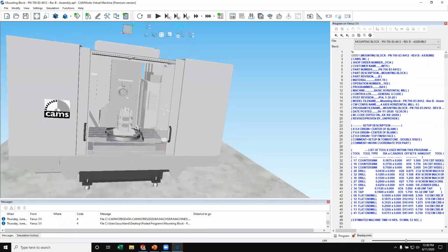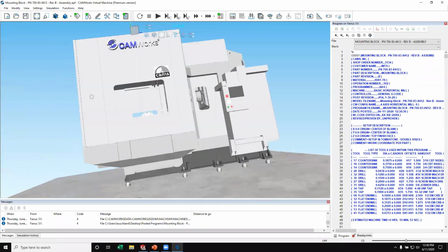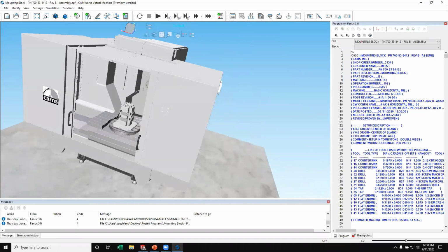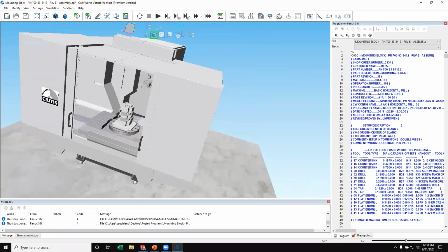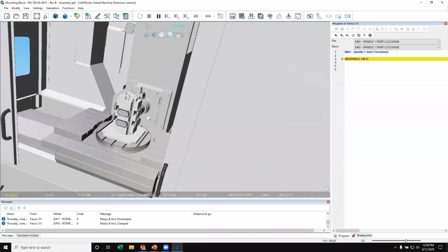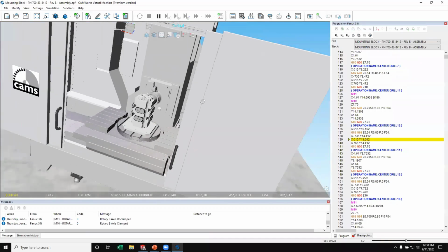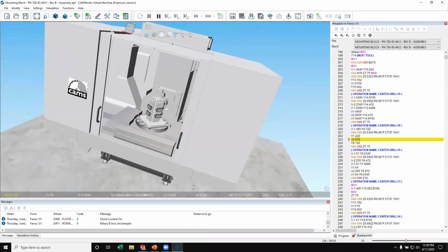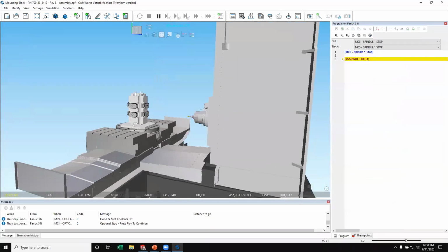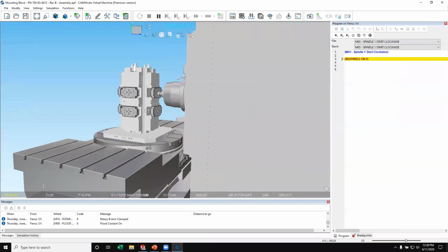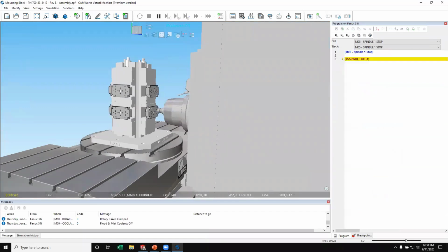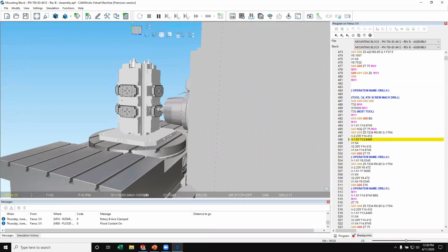We've got our CAMWorks basic horizontal mill here set up to kind of mock that. And we're going to go ahead and hit play. We're going to let this start running the program, and you'll see it kind of move around. We can zoom in. You can see that guy index different rotations to drill in those holes. And we're going to do a trick here that every operator wishes they could do to make things easier to see. We're just going to get rid of the enclosure on the machine. I know that's not realistic, but every operator wishes they could, until they get a nice coolant shower. But yeah, it makes it easier to debug and see the program run. So it's a neat feature, but a definite upgrade.